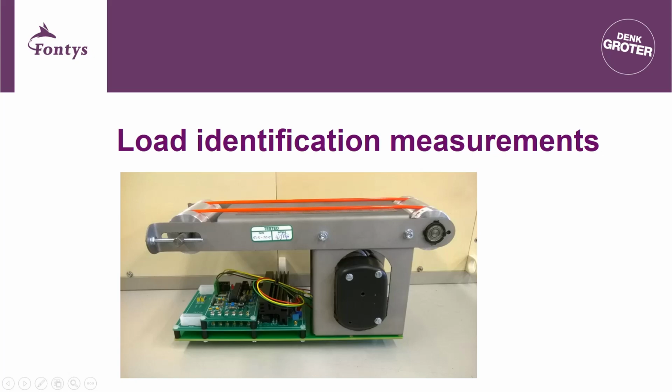Hi everyone. As a mechatronic designer, you are often responsible for choosing and determining a transmission in an electromechanical drive system. An example is this conveyor belt that is moved forward by means of two pulleys over here. Practical examples similar to this are a scanner, a wafer transport system, conveyor system, or a printhead carriage in a printer. But to determine the motor and the transmission, you must first know the load torque.